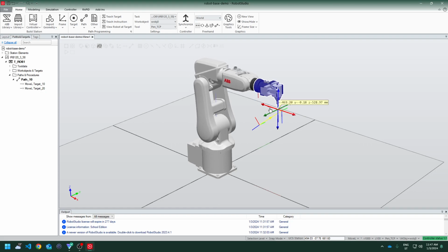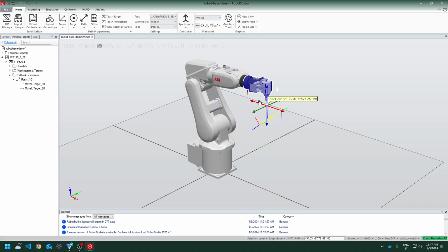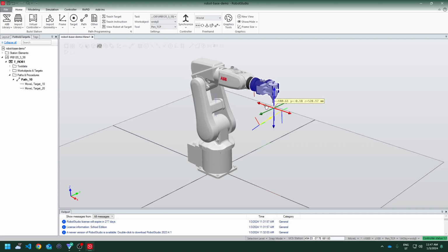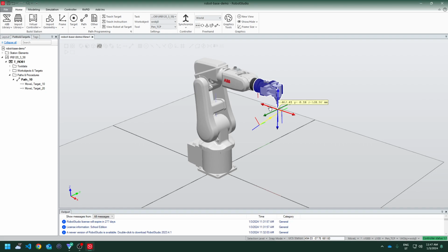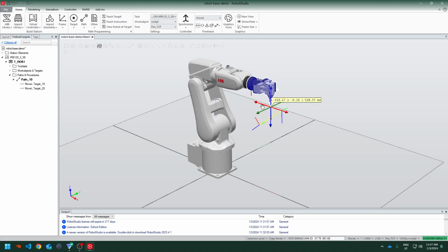If you were in class when I showed this demonstration, I talked about singularities. Singularities happen when the robot's configuration dictates that it moves infinitely quickly, depending on its configuration, the movement, and the speed of the movement. This can happen. So you can see that this robot will flip up immediately.